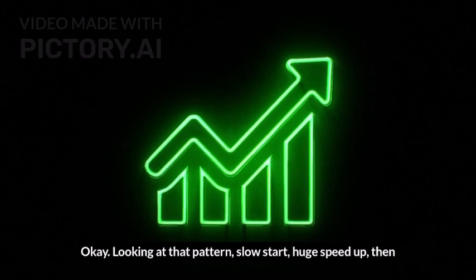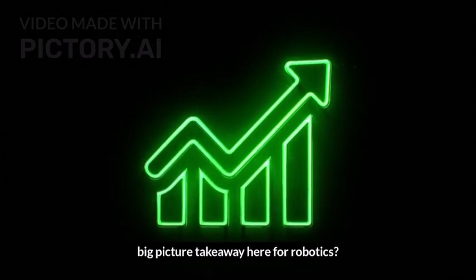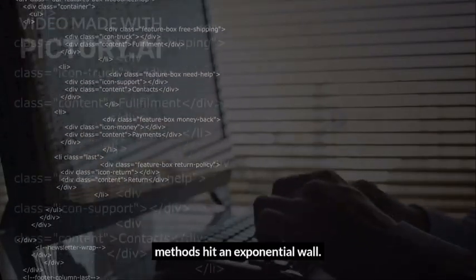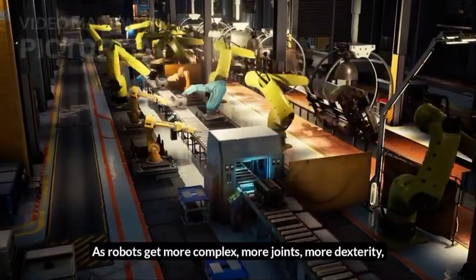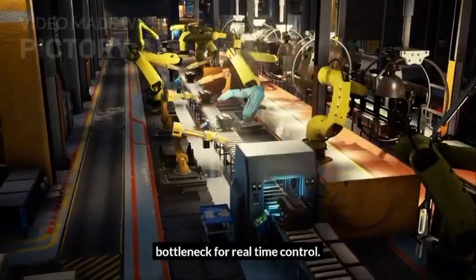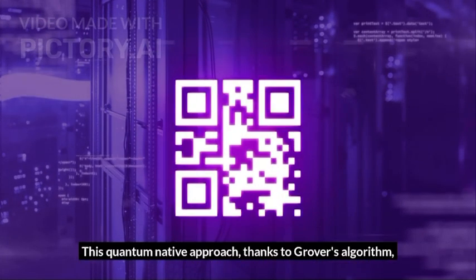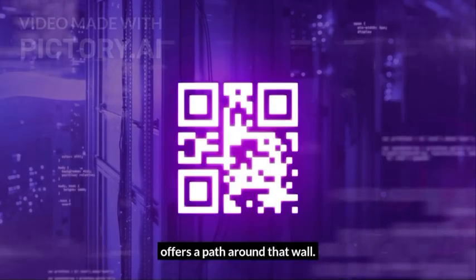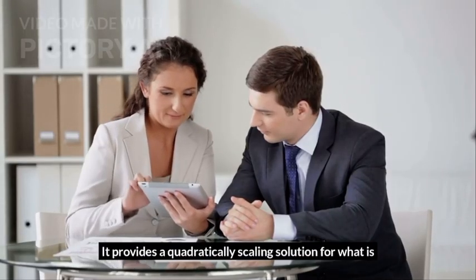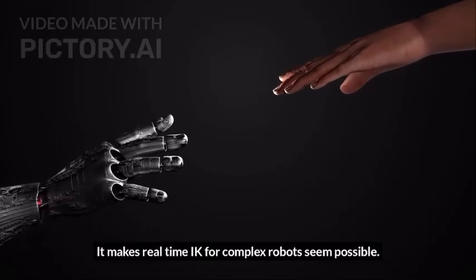Okay, looking at that pattern, slow start, huge speedup, then still significant speedup. What's the big picture takeaway here for robotics? The takeaway is scalability. Classical methods hit an exponential wall. As robots get more complex, more joints, more dexterity, classical computation becomes the bottleneck for real-time control. This quantum-native approach, thanks to Grover's algorithm, offers a path around that wall. It provides a quadratically scaling solution for what is fundamentally a search problem. It makes real-time IK for complex robots seem possible.